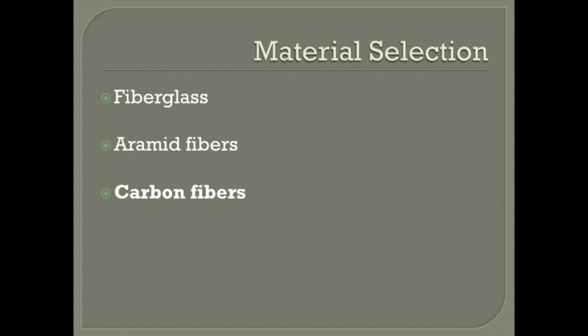Of the three composites considered, each has its own benefits. Benefits to choosing fiberglass are that it has a high strength-to-weight ratio, good environmental resistance, and good flexibility. Aramid fibers are durable and have high tensile strength. Carbon fibers, meanwhile, are versatile and can be used in other parts of the helicopter, are stiffer so that they have better turbulent airflow resistance, and have a high modulus to withstand high flexural loads, but they are much more expensive. In the case of military helicopters, carbon fiber and epoxy will be the composite of choice for the rotor blades.